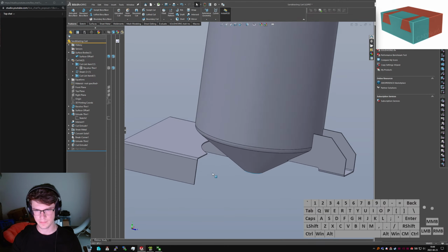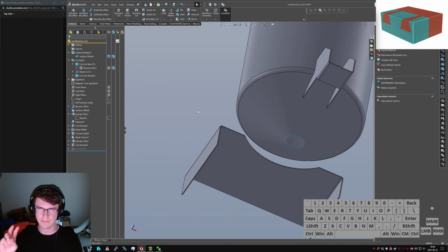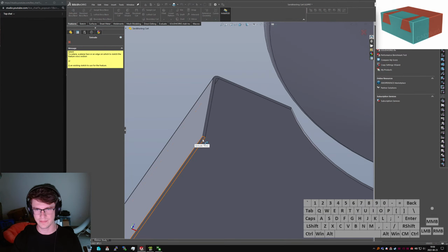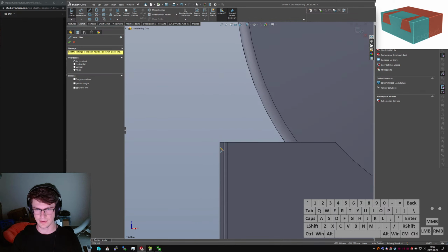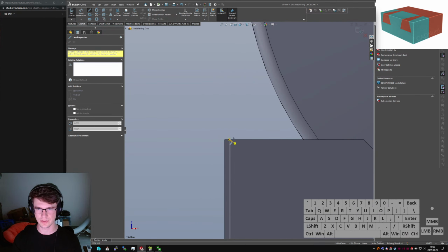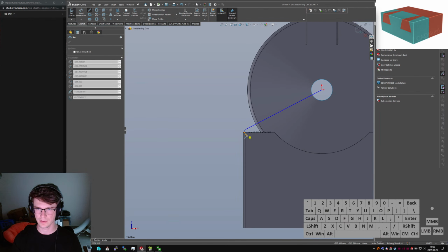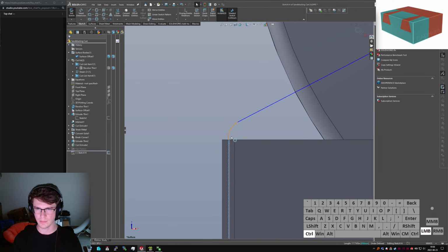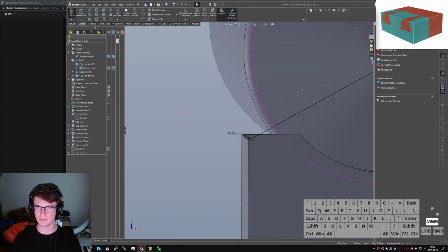to clear everything. And now, because we're working on just a regular solid, I have to be a little more careful about how I do my thin extrudes, because I don't have any of the kindness of sheet metal tools. So I'll start with something coming off the origin here. Go directly to that. Make this guy tangent. And, whoops, come on, let me add a dimension, please. Thank you. 5mm, looks good to me.